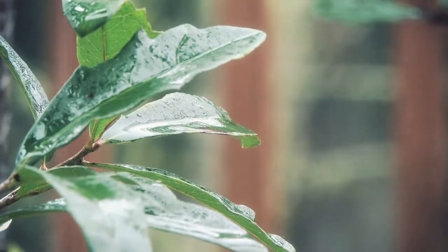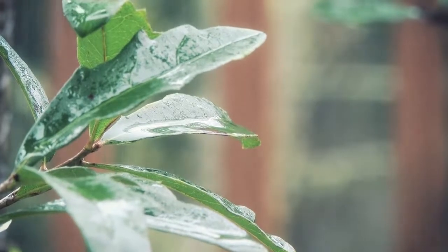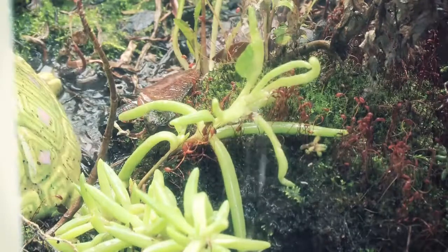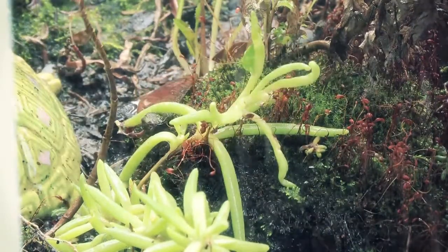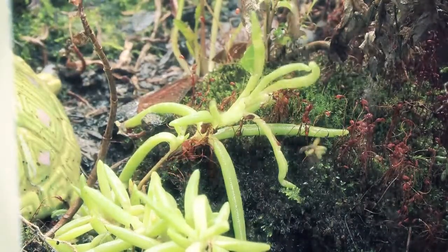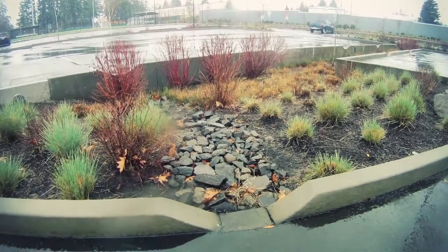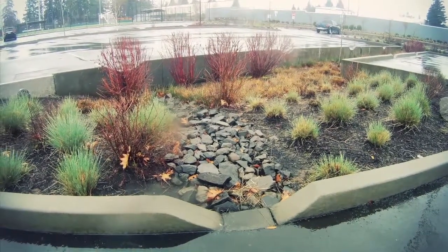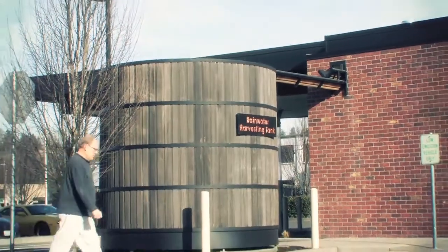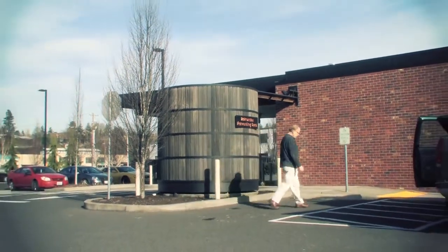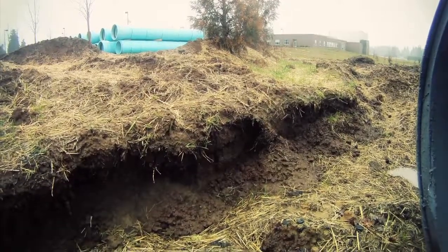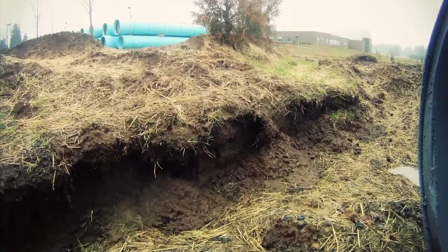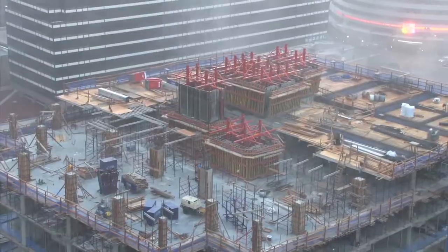Design teams using rainwater management option 1 should use an empirical, statistical, or mathematical method to confirm that the total volume of rainwater managed by the project's green infrastructure and low-impact development measures will fully manage the total runoff volume through infiltration, evapotranspiration, or capture and reuse. Calculations must account for the site-specific soil characteristics, the soil infiltration rate, and the storage capacity of all measures implemented.